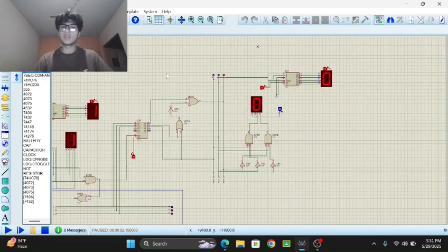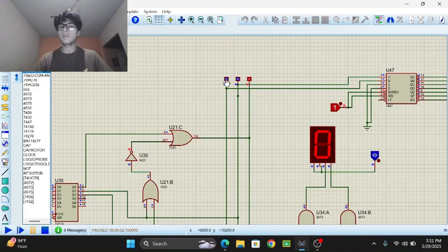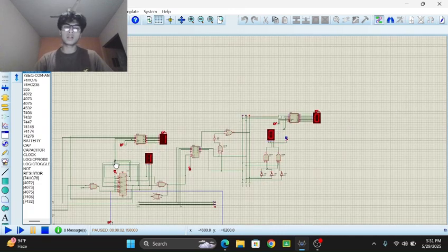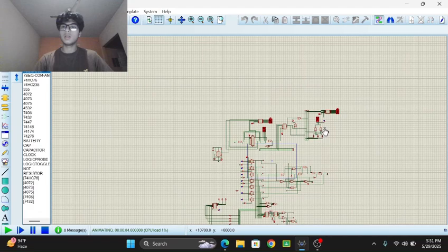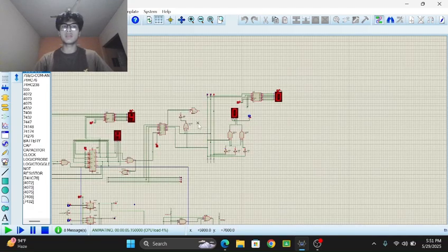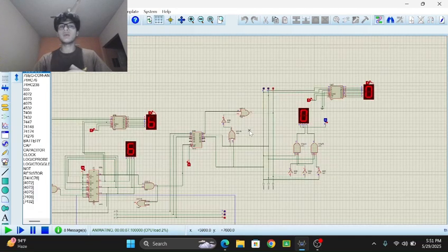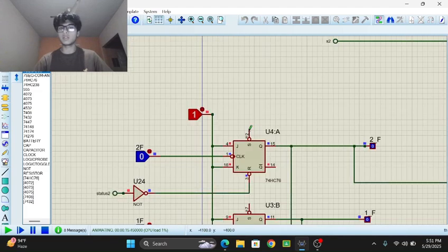So this is our display unit. It takes the user's output S0, S1, S2 and outputs it using a 7-segment display and a clock system that gives a 10-second delay or a timer. So now if I resume my system, the clock will start incrementing, and once the 10-second delay has been completed, signifying that the elevator is now moving, we'll see how it changes, and it instantly goes to our second floor, and it will retain this input until a new input arrives. Why? Because these JK flip-flops have a reset connected to them specifically towards the second floor or our status 2 probe.